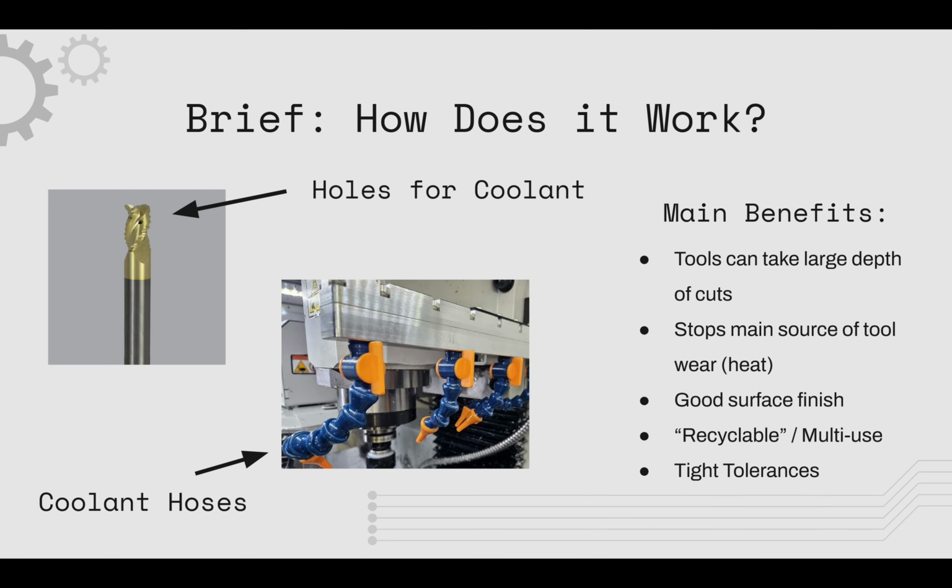This works by flooding the cutting surface with a fluid either internally through the tool or externally through hoses. Benefits of using cutting fluid allow for greater depth of cut, keep the tool cool and from experiencing excessive heat, and give better surface finish and tighter tolerances as well.